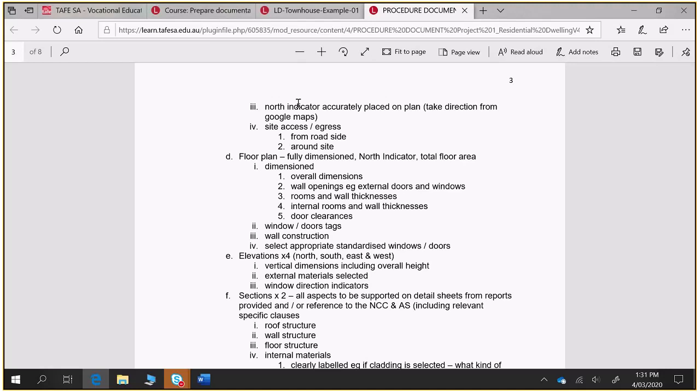No answer to that? Well, you don't have to show a north arrow on every page. If you're showing it on the site plan, do you need it on every one? You should still have a north arrow on your floor plans. What I've always done as drawing practice is have a north arrow on any plan, unless it's like a kitchen plan or bathroom plan, where the north arrow doesn't matter because that context is expressed in a larger drawing from which it is taken. A floor plan is essentially an extension of the site plan in that way as well. But I've always had north arrows on my plans, except for the small detail ones.